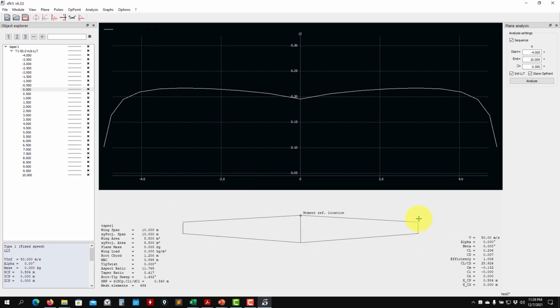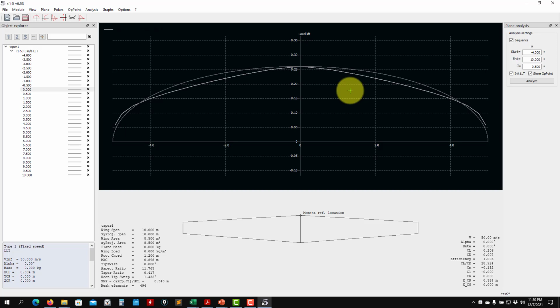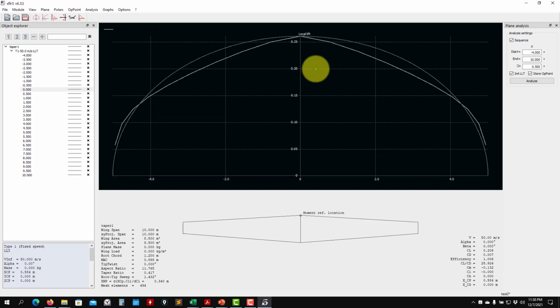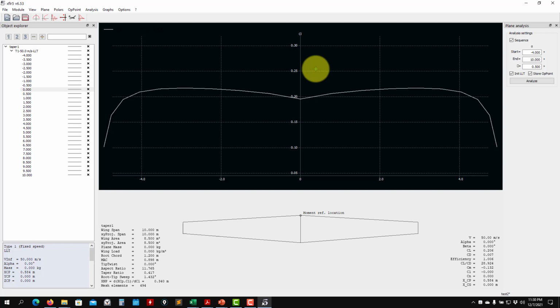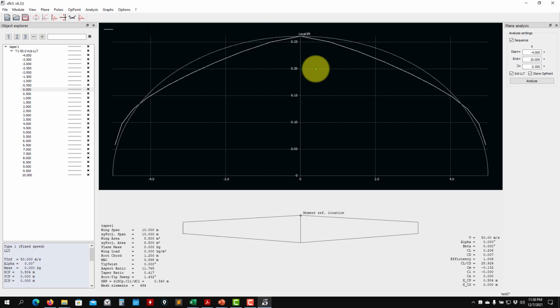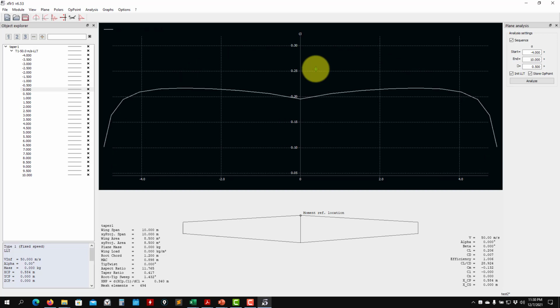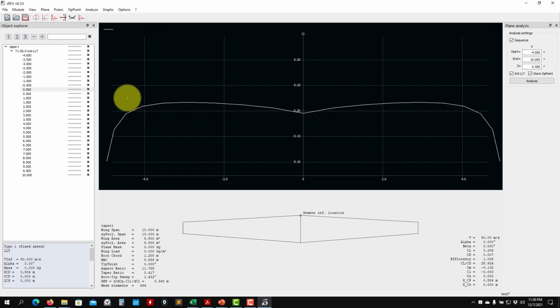We saw that one in the review, also the theory, that is more loaded towards the tip when we look at the CL. So remember that when it comes to CL, you want a uniform distribution, and if you look at the lift, you want something that is elliptical. Okay, so you can use CL to control the stall progression, and lift to control the ideal distribution. So see here that this is not very good because you are stalling first towards the tips, and that is not ideal.